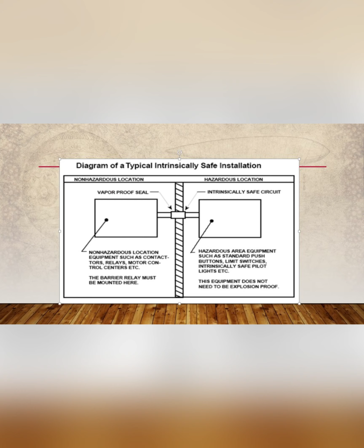So this is a SAAB tank radar. The figure shows the diagram of the circuit and also the schematic circuit diagram. It consists of workstation, I/O box, level unit, signal board, processor memory board, interface board, backup display, transmitter interface, power block, and also transmitter. This is a diagram of a typical intrinsically safe installation.